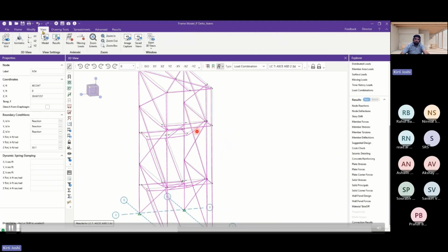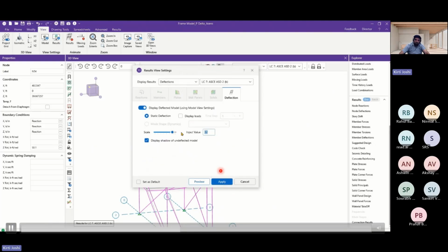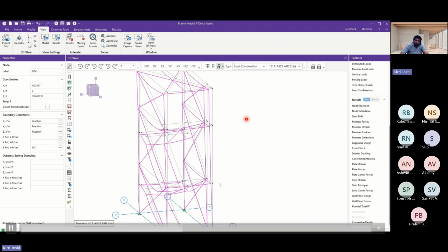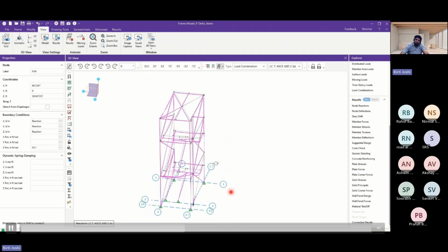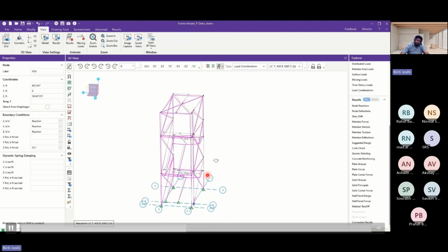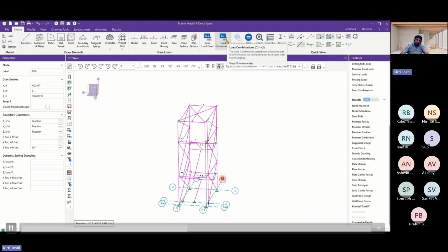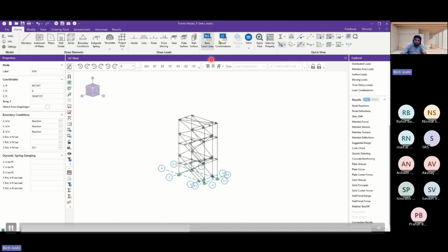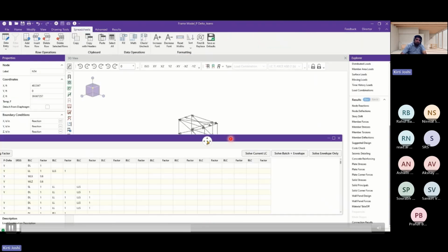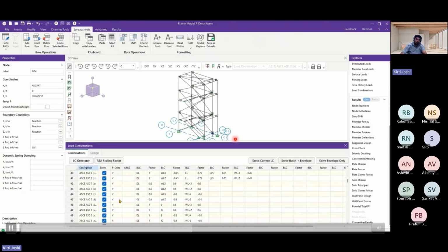So we'll check the deflection limit, but even using the deflection feature, I'm not getting a proper way to tell whether it's coming from the flexibility or not. So I set my deflection limit to 90 so that I can zoom in a bit more. From this also, on the columns, we can see the deflection shape. But this also doesn't help me find the exact issue.